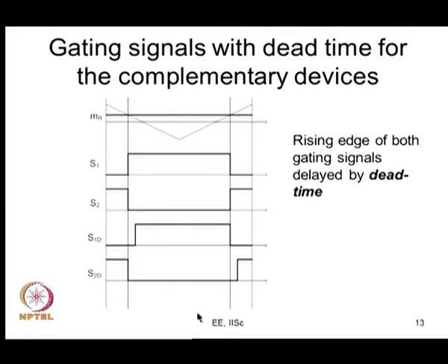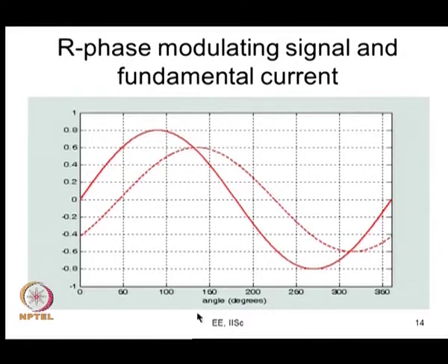Alright. So, it depends on the current direction. Where there is a change in the current direction, it is negative here, it is positive. Remember, we have ignored the harmonics here, that is alright, it is a reasonable assumption which we have made before. We did this when we were calculating conduction loss, when we were doing DC link current analysis, when we did switching loss. In all these cases with high switching frequency, we have ignored the ripple; there is nothing wrong in this now.